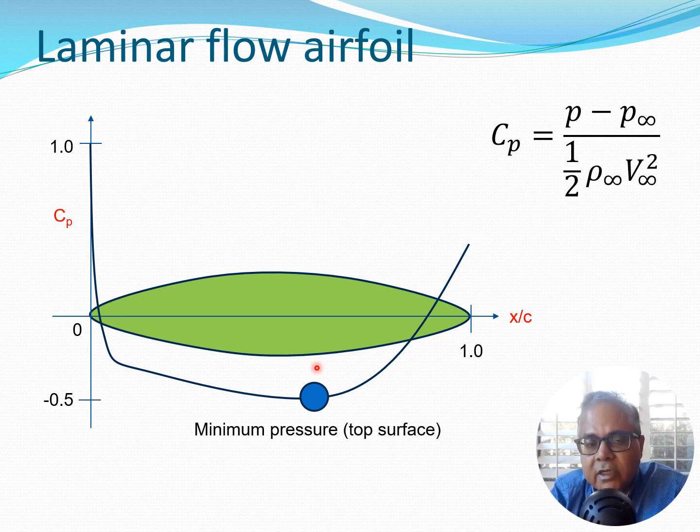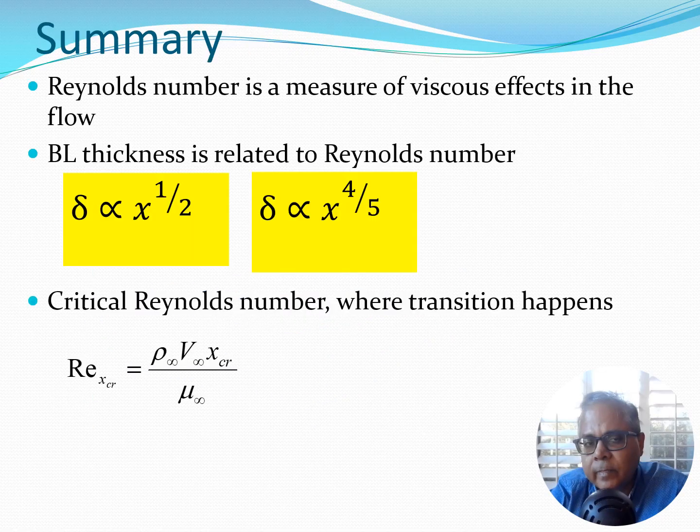but do remember that if there are any kind of discrepancies or any manufacturing defects or any corrosion on top or bottom of the whole airfoil section here, then that would have deleterious consequences for this particular type of airfoil section. But there are certain situations, certain flight vehicles where a laminar flow airfoil may actually be useful.